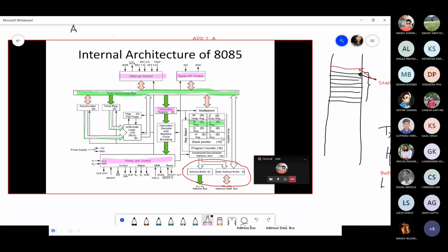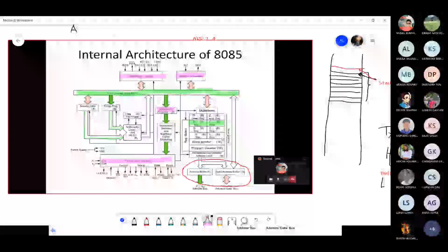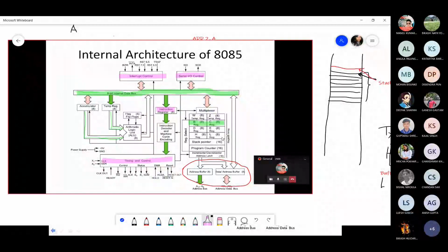So this is all about the architecture of our 8085. To summarize it all, we have the ALU, which performs all the operations. We have some program invisible registers, one of them is operand 2. Temporary registers are not visible to the programmer, but they are used to do some rough work or store temporary results. Accumulator is the most important or most commonly used register. In the 8085, with all instructions, the accumulator is always used.